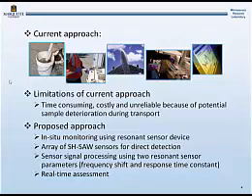And one important point is that for the signal processing we use two resonance sensor parameters. So one of them is the usual equilibrium frequency shift, and the other one is the response time constant, which is rarely used, but which is really characteristic for a particular analyte. So it greatly increases our selectivity for each BTEX compound. This also allows us to do real-time assessment of the situation.